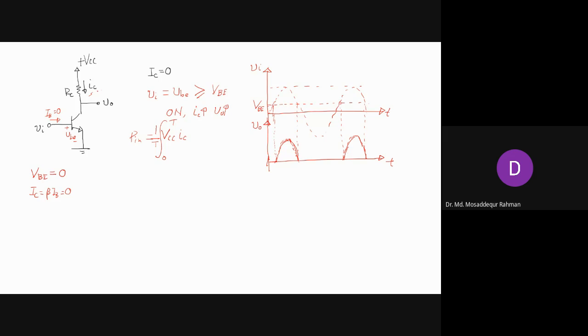Okay, now this is for the regular amplifier. At the output stage, this is a common emitter amplifier, right? We have explained the concept and the limitations of our regular amplifier in delivering high power to the load. This is our common emitter amplifier, but at the output stage, we usually have common collector. So how does it work out for common collector?